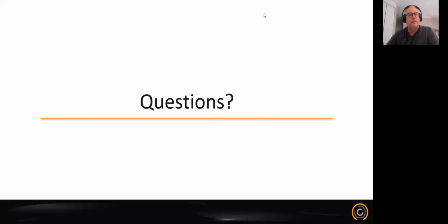Good question. You have to go back to the assumptions that I mentioned at the beginning. All these things assume that the soil is linear, elastic, and is all the same material with respect to depth. The actual loads will probably be much lower than what we're estimating in these values.